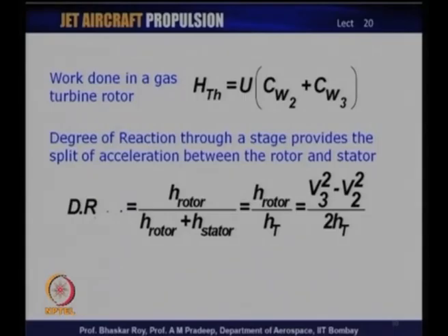Now, if you can quantify, then you know how much acceleration you can do in a rotor and how much acceleration you need to do in a stator. In the stator, we have seen that we need to accelerate to the extent that the flow goes sonic at the exit of the stator, and then we can do a lot more acceleration in the rotor all over again.